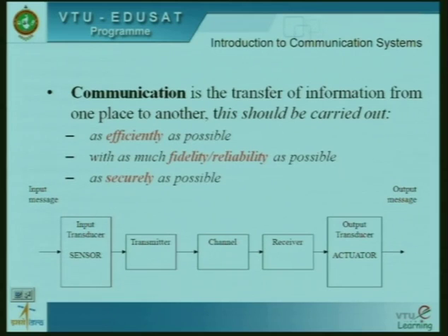If a signal has to be launched onto a channel, we need a transducer there, which converts an electrical signal back to a physical quantity. In our case, the channel accepts an electromagnetic wave. To convert an electrical signal to an electromagnetic wave, we use an antenna. An antenna is basically a short conductor which takes in alternating current and converts that alternating current to an electromagnetic wave, and that is what forms the transmitter section, or what we call the source.